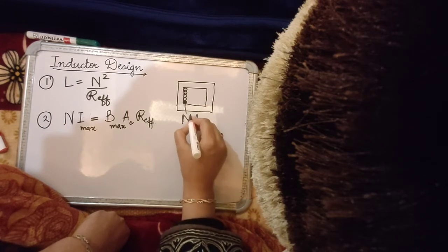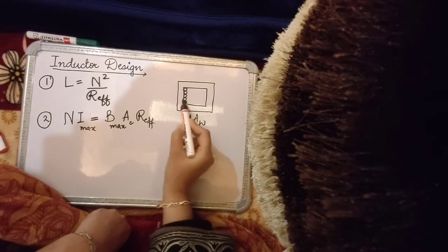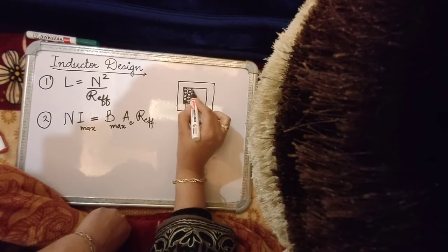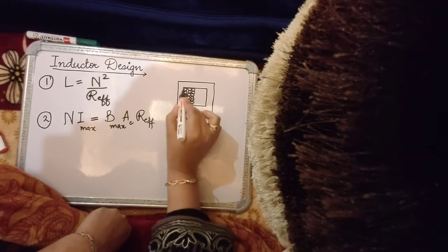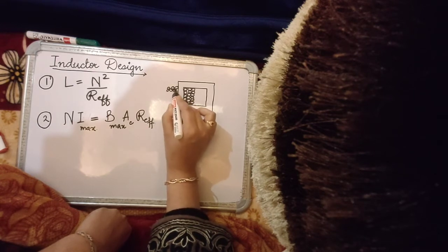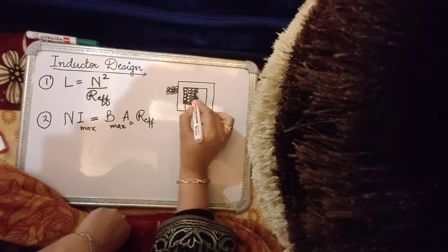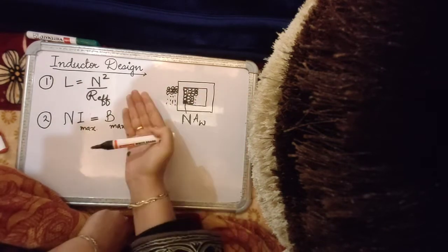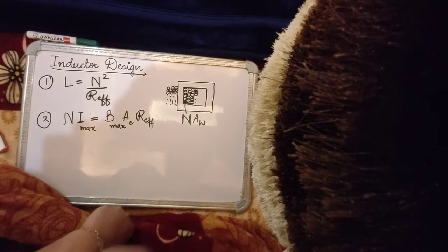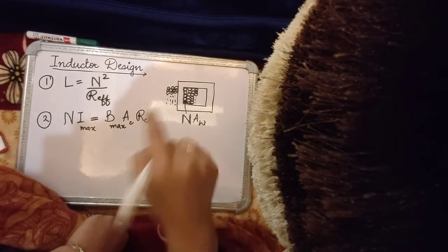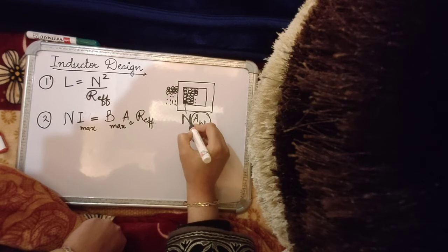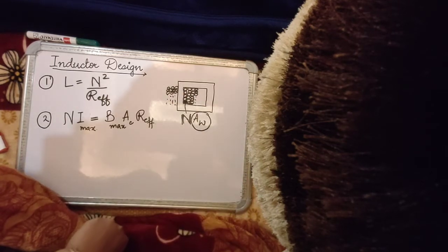Sometimes you may not just have a single winding, but you will wind it once, and then you will increase the number of turns by winding over those turns. So in that case, you can have multiple conductors, packed like this to increase the number of turns over the same limb. Of course, they will be existing over this side also, right? Something like this, so on and so forth. So this is a cross section of the core along with the conductor that I have cut, and this area is the area occupied by the conductor, not the core, but the conductor. So this is the area of cross section of the wire or the winding, and the total number of turns gives you the total area occupied by the conductor.